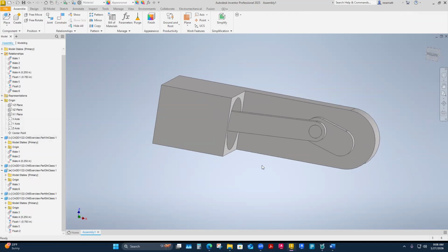You'll get some errors if your constraints did conflict with how that part grew, if you had something locked down. Like really, if I had a dimensional constraint between something here and that, and it wasn't going to allow that part to grow, you'd get errors with those constraints, and they show up as exclamation points on your constraints, and they have to be reconstrained. They're editable, like I said, your constraints are editable, just like a feature.